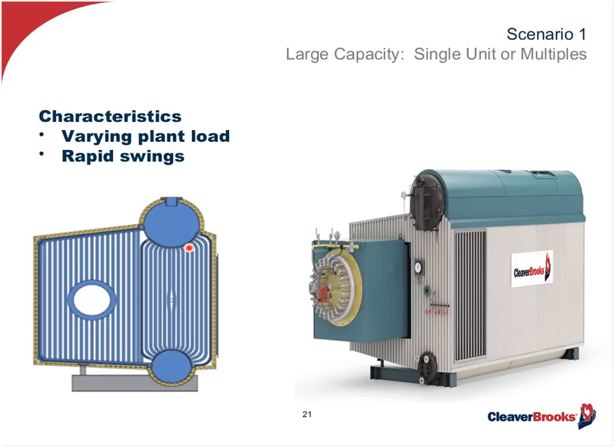Because I don't want that pressure to drop, okay? As it begins to drop, I want to make sure that I modulate to that firing range to get the circulation I need to take the heat away from the burner and give me the steam that I need.